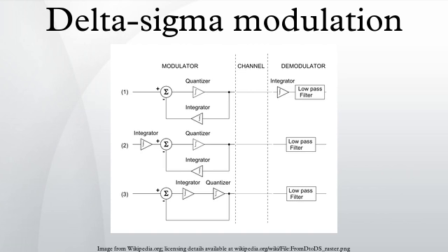Digital-to-analog conversion. Discussion. Delta-sigma modulators are often used in digital-to-analog converters. In general, a DAC converts a digital number representing some analog value into that analog value. For example, the analog voltage level into a speaker may be represented as a 20-bit digital number, and the DAC converts that number into the desired voltage. To actually drive a load, a DAC is usually connected to or integrated with an electronic amplifier. This can be done using a delta-sigma modulator and a Class D amplifier.